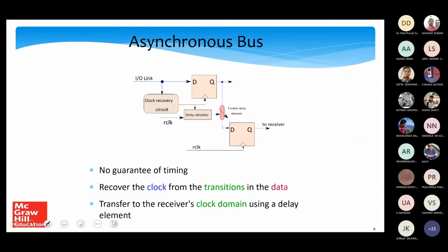And you have asynchronous processes where clocks are not necessary or not transmitted. So here Professor Sarangi actually says exactly the same thing which I have been saying. That's a PLL. He calls it a clock recovery circuit, but it's usually implemented using a PLL.